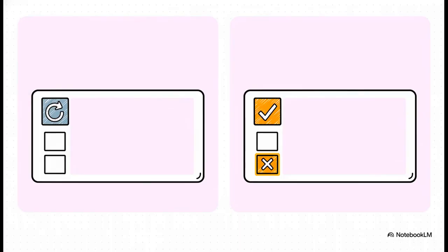Now, a quick heads up here, you really need to know which software version you're running, because the exact toggle commands differ slightly. For the standard configuration, LSK1L toggles the display on and off. But if you're running software versions SCN 1000.3 or 1100.3, it's split up. LSK1L will enable the display, and you actually have to press LSK2L to disable it.